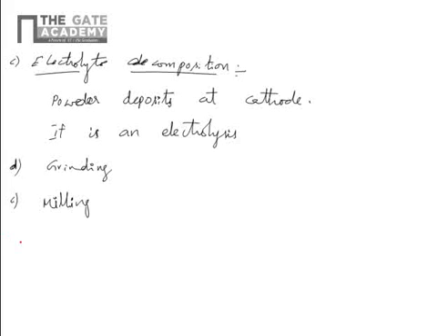So after getting metal powders, powders ranging from 1 mm to 1 micron are accepted. Because in any of these processes, the powder size is not constant for each particle. Because there are different sizes of particles, they are sometimes distributed unevenly. So to distribute the size of the particles evenly, we use blending or mixing.